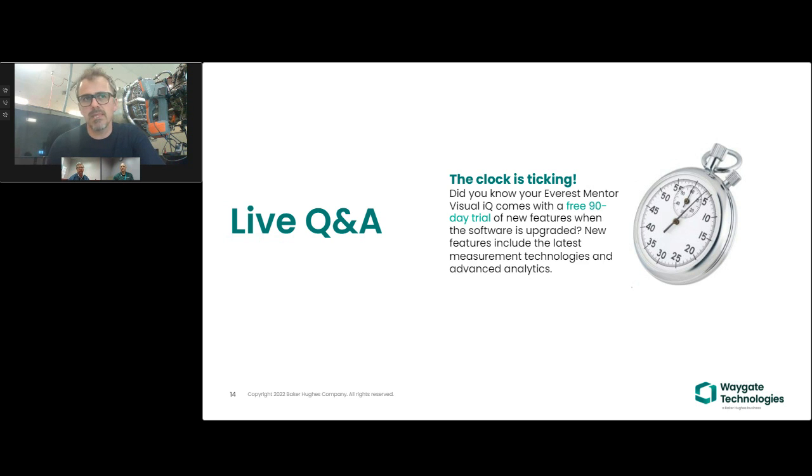A key feature in that suite of tools is dark boost. Press the dark boost button, a slider then appears on the screen, increase that value, and that will illuminate those darker, far view images much more. That's a very useful tool, especially in large cavity applications such as combustion chamber inspections. So a range of things that you can do from a hardware and software perspective.